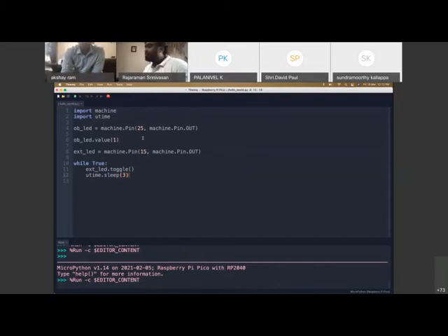It's actually still running the same blinking thing that we had implemented some time ago. So anytime you try to run something or try to open it on the Raspberry Pi Pico, and then you get this message, it means that it's already executing some code. So you need to stop it.